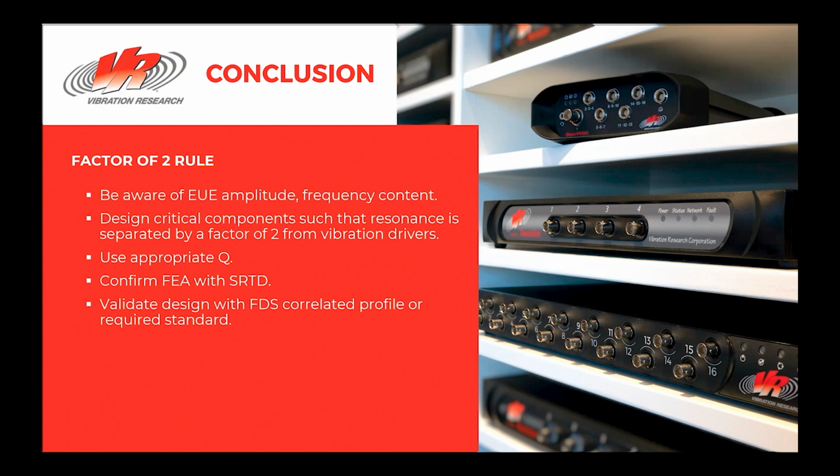Confirm finite element analysis with sine resonance track and dwell functionality of vibration research software. Validate design with fatigue damage spectrum correlated profile or required standard. And remember to confirm resonant characteristics of vibration test fixtures. Can't overemphasize the need to have a good test fixture when you're running your vibration test. So even if you have a wonderful profile and you have it in good control, or you think you do, if your fixture is not imparting energy properly, then the test results will be questionable.